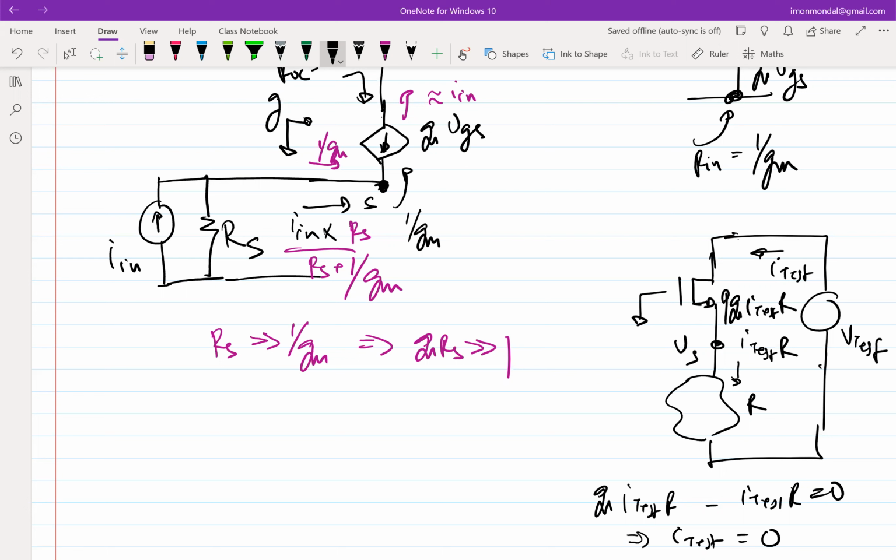Infinity, right? So by putting something at the source, I am even making it worse, in the sense that I am adding extra. So it should not become finite now. Correct. So that's why, looking into the drain of a transistor, you have infinite resistance, ideally.